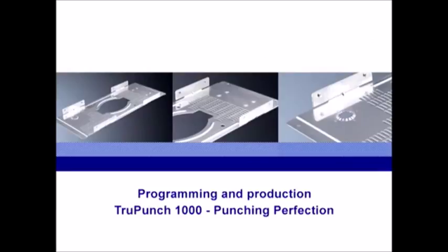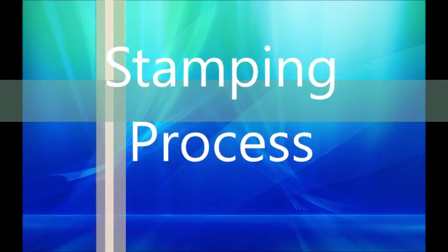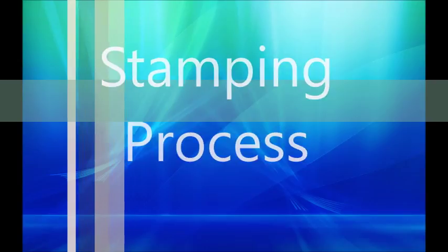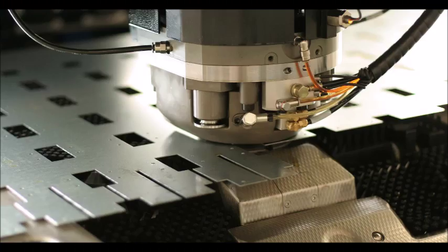And that was the punching process. The next one is the last one, that is stamping process. What is stamping process? Also known as pressing. Well, this process is of placing sheet metal, either blank or coil, into a stamping press, where a tool and die surface forms the metal into a new net shape.